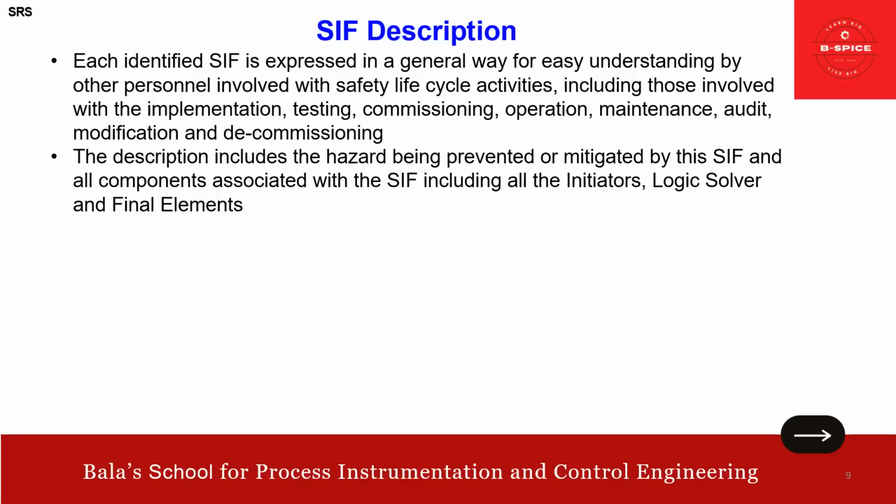So that is a point. The description also includes the hazards being prevented or mitigated by the SIF and all components associated with the SIF, including initiator, logic solver, and final elements. All these also should be part of this SRS. Okay, friends?